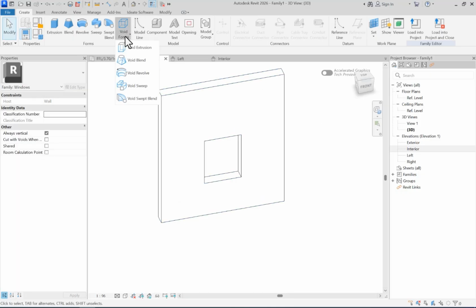Now, as for the form that I have in mind, guys, let's say, for example, I want to get two diagonal forms or like two curves on two sides of this window. Yeah, let's go with that. Or even all around the window. Why not? By the way, I just mentioned two forms and I have two different techniques for them. More precisely, to set the form all around the window, we can use sweep, and to set this on only two sides, we can use extrusion.